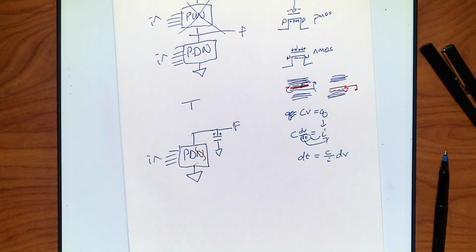How does the capacitor powering down give us an advantage? Because it forces you to be fast. We want its best operation to happen when this is very, very quick. I can speed this whole thing up by making the capacitor smaller. If you need a little more time, make the capacitor a little bigger and it slows down.